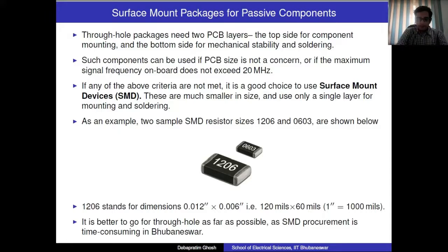It is because at very high frequencies, even the long legs of these components start acting in a parasitic manner. These legs, which we very conveniently assume as good conductors, will exhibit tendencies of an inductor. So therefore, what you will have is not just resistance, you will have a resistance plus a j omega L component which will add to the parasitic. And as the frequency increases, the parasitic inductance effect will also increase.